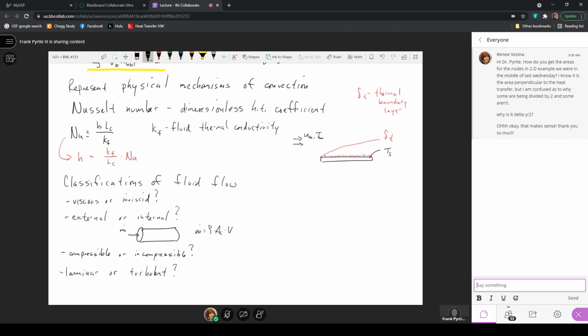And we would consider, is it a laminar flow, where in the laminar flow, it's dominated by viscous forces, and the turbulent flow is dominated by inertial forces, and we would use the Reynolds number, where that Reynolds number, once it reached a threshold value, we would consider it to become turbulent, where at the lower values it's laminar.